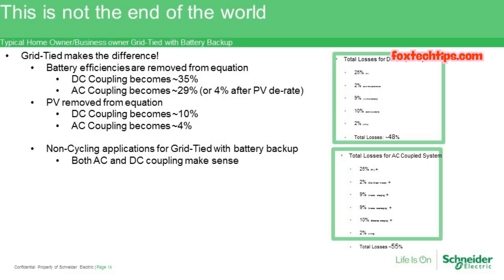In particular, it could be that a grid-tied system is a more efficient way of doing it over the long run. We're not talking about 2 or 3 years, we're talking about 10, 15, 20 years, that with daytime air conditioning that's very consistent, we're going to be able to offset that more. So is there a big difference between a grid-tied system and a battery-based system? Yeah, there could be. That 98% efficiency versus, say, 85% efficiency for a battery-based system could come into account here. The thing to note, though, is that with a battery-based system, the efficiency is much, much better than a grid-tied system when the power goes out. And so that's where AC coupling comes into effect.